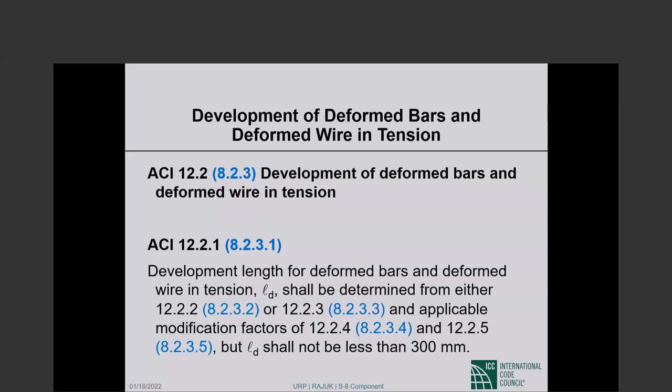That bond is low, very easily overcome. That is why, already in the 50s and 60s, we switched to deformed bars, where the ribs greatly improve the bond between the reinforcement and the concrete. Today, basically all reinforcing bars are deformed.